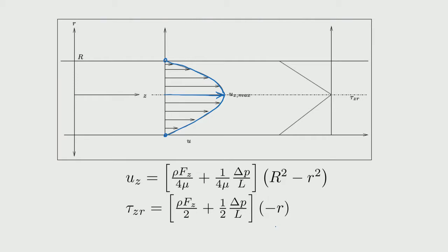Now, you can already see that from Newton's law, the slope of the velocity profile should indicate what kind of shear stress is present at that particular location. So, you can already see that the slope is 0 here, which means that the shear stress is 0, and then the slope is actually here. So, it appears as if the slope is changing sign when you go from here to here, but please remember that this is actually a cylindrical case. So, this is r and this is also r. Okay. So, because of that the slope actually has the same sign on both sides, and that is negative.